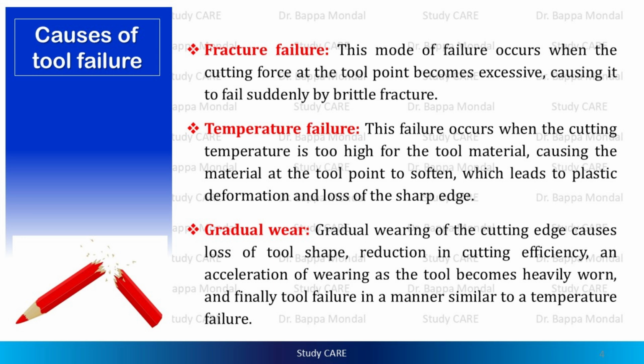Gradual wear. Gradual wearing of the cutting edge causes loss of tool shape, reduction in cutting efficiency, an acceleration of wearing as the tool becomes heavily worn, and finally tool failure in a manner similar to a temperature failure.